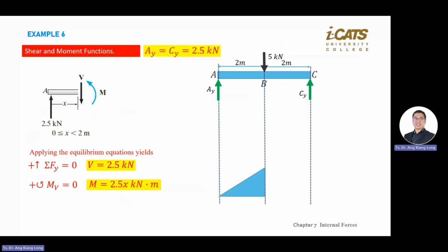You copy your free body diagram, then draw the dashed line through your point A, point B, point C. Then start to draw the axis. If I set the question, there are marks for all these hidden lines and also the axis. You need to label V in kilonewton, because the forces you see in the question are in kilonewton.